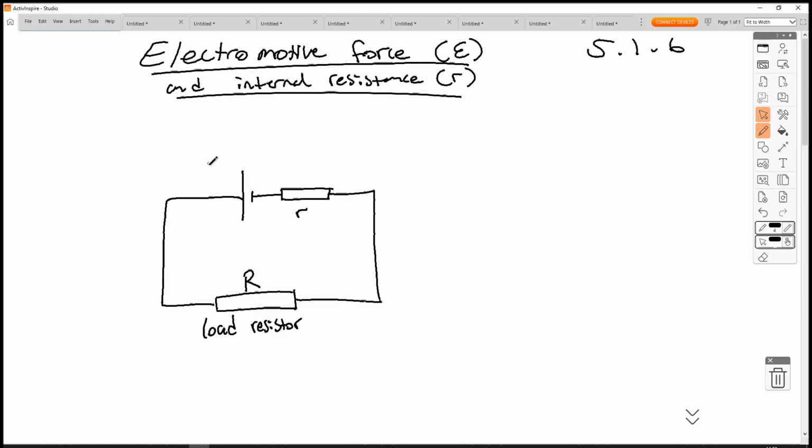So what I'm telling you is that if I drew this as a battery, and I've even drawn the little nib in the middle, because if you've got an AA battery, you've got the little nib on the positive side. So that's what a battery would have inside it. An ideal cell generating an EMF, so we'll label that as epsilon. A small resistance, little r, and a big resistance on the load.